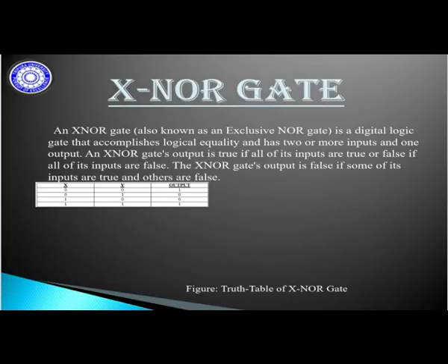XNOR gate, also known as the exclusive NOR, is a digital logic gate whose function is the logical complement of the exclusive OR gate or XOR gate. It is equivalent to the logical connective from mathematical logic, also known as the material biconditional. A high output, that is 1, results if and only if both the inputs of the gate are the same. But if both the inputs are not the same, the output results as 0.